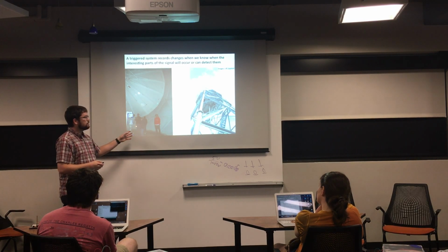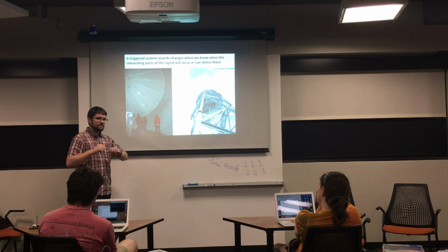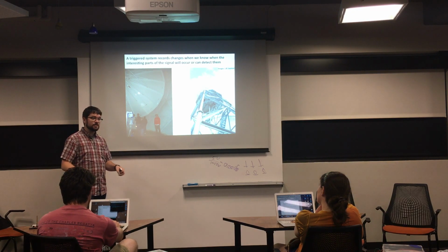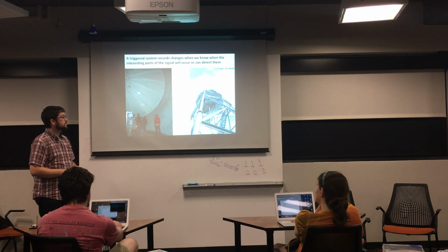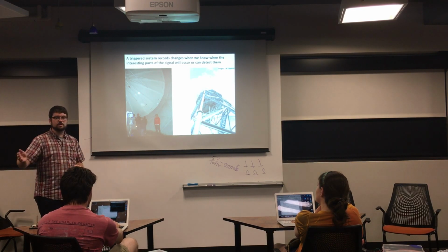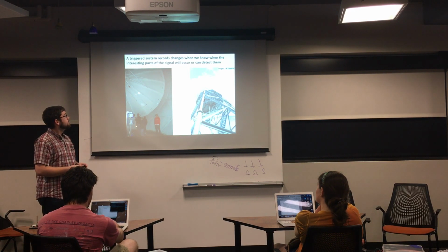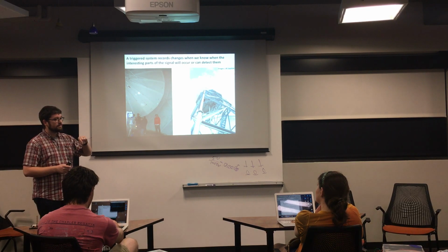Right? So this is like what you do in active source seismic, where you hit the hammer, it triggers the system, it records for so many milliseconds, and then it stops. Because you only care about the interesting part when you actually hit the ground and put seismic energy into the ground. You don't care about the continual recording for an active survey like you would passive seismology. So this is really generally used for very high frequency recording rates.